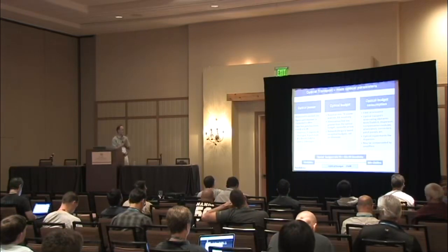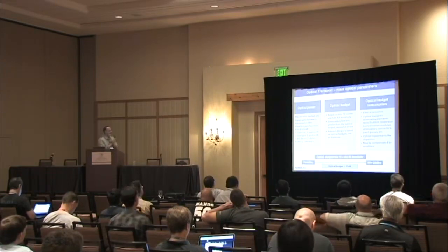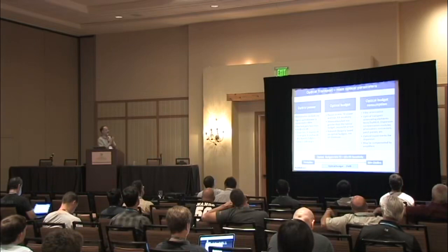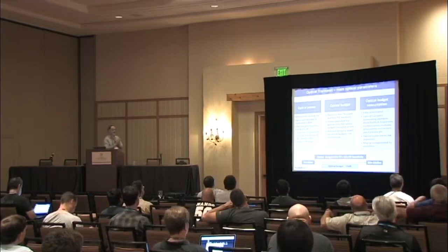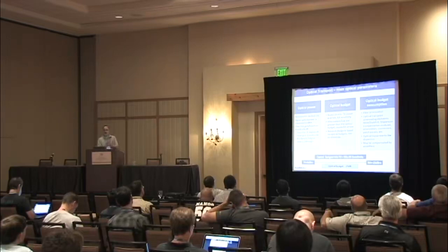of an optical transport. First of all, optical power is measured in decibels. Signal optical power is measured in dBm, decibel-milliwatt. And the fiber link loss from A to B is in dB. If you have a power loss, you incur an attenuation, it's negative dB.